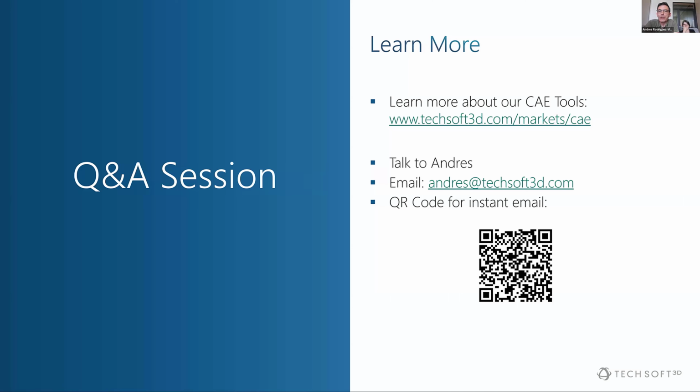But the question is, does CEETRON support implicit surfaces directly? The answer is no. CEETRON Envision comes with various data models for unstructured grids, especially on the web, very specific models to optimize that. And it also provides a geometry model, but they're all tessellation based at this point in time, of course.